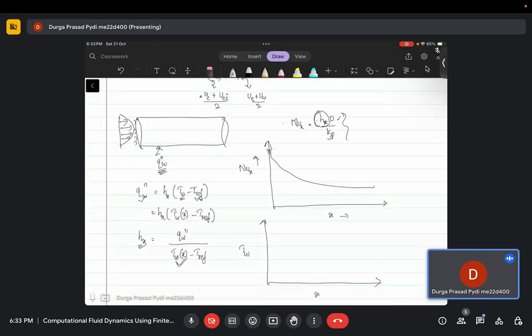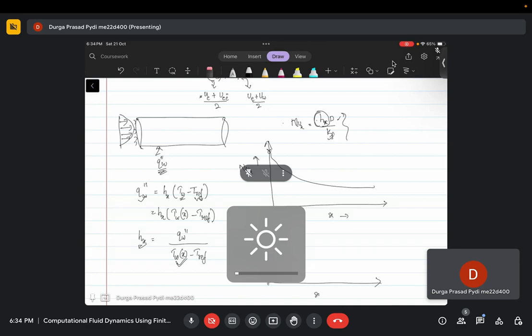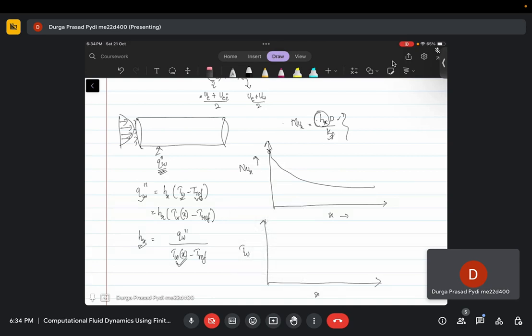What are the boundary conditions you have specified? How do you specify your inlet condition? Is it a parabolic profile or a uniform one? Uniform. What is your inlet velocity? Temperature is 293 Kelvin. No, velocity. Velocity 0.005 meter per second. So basically, you are giving a uniform velocity, not a parabolic profile as an input.